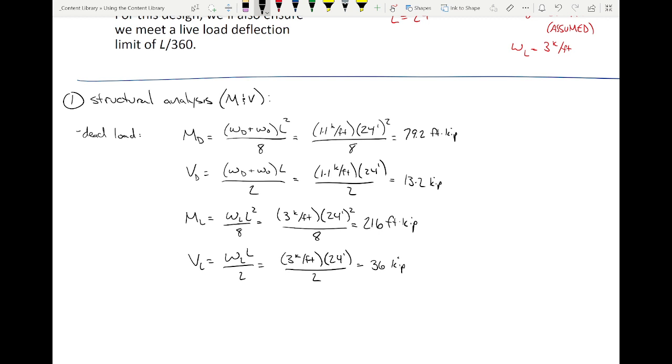And again, we might have saved ourselves a little bit of time if we had factored the loads and just did wL squared over 8 once and wL over 2 once. But I want you to be in the habit of thinking that you need to do dead load and live load separately. Because if a beam has a point load at midspan, and you think, I know what I'll do, I'll take that point load and turn it into a distributed load, right? Remember, that's the method where Dr. Mike is going to slap my hand. Don't do that. No. Ow. I'm a dork, I know.